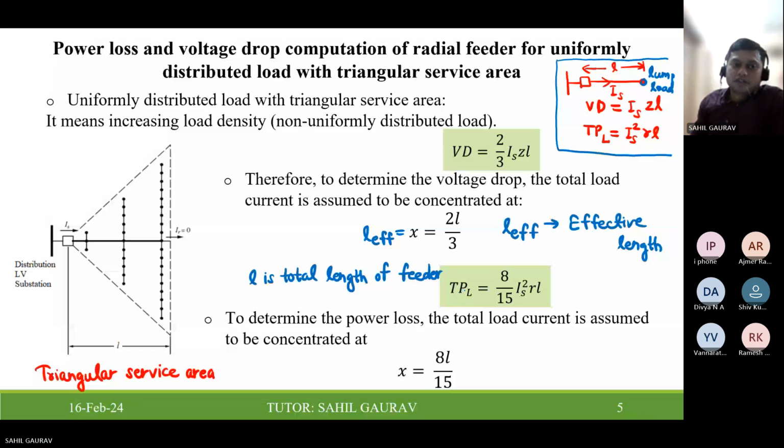Like you just remove these loads. These are nodes, and where these load connections are there. So you just removed all the nodes. Now you have to provide the power to the load at which point shows that voltage drop will be similar to this lump load connection. So you will have this lump load at single point.